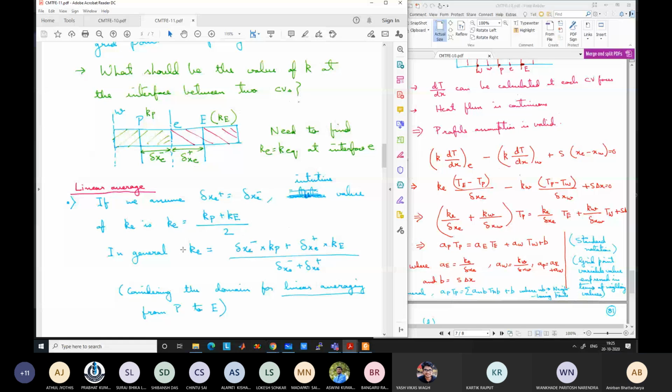Even if you have a very fine mesh near a jump where there is some conductivity jump, it is still going to work. If there is no jump in conductivity, with a single material like air or water flowing through a pipe, as we generally do, sudden jumps are not there unless we are treating some composite material, like I was saying, metal fin PCM composite. Unless it's a composite material, in most cases this is going to work.